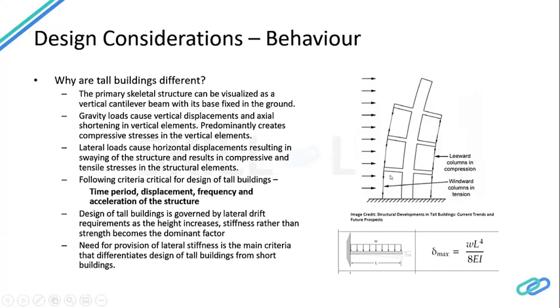I'm going to compare the building to a cantilever beam here. Now, as you can understand, any building, short building or tall building, is basically a cantilever structure with the base considered as fixed and the top end the free end of the cantilever, similar to what you see here for the cantilever beam. There's one fixed end and one free end.